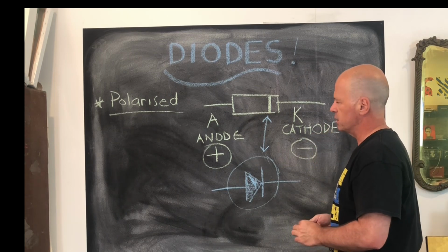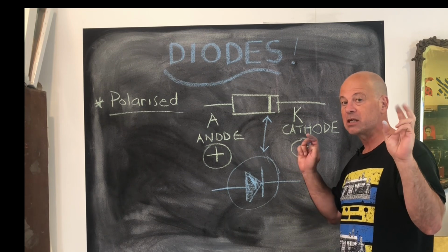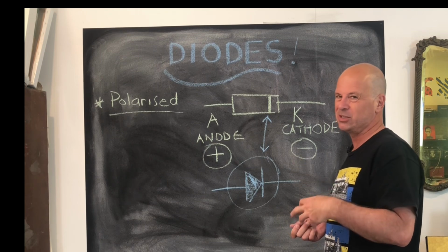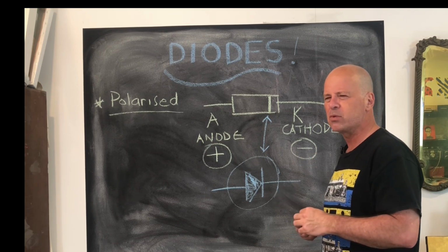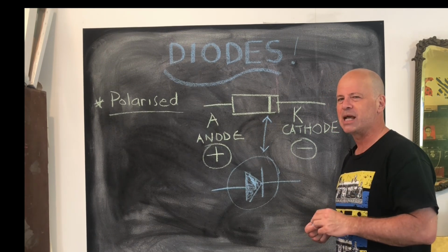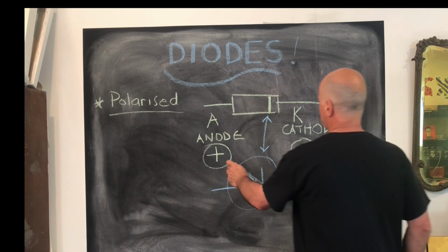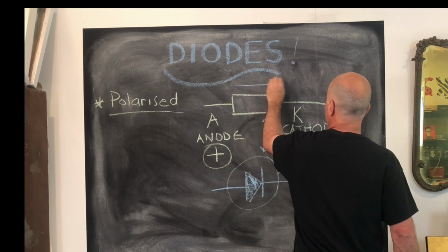Another thing to remember is quite often in electronics, we're dealing with what's known as conventional current. Some people say that's the electrons flowing in the opposite direction. I think it's an historical accident. I think when they were first playing with electricity, people thought it was a flow of positive charges, and that mistake has stuck till the present day. So for conventional current, we've got our positive end here, our negative end here. So our conventional current is going to flow in that direction.